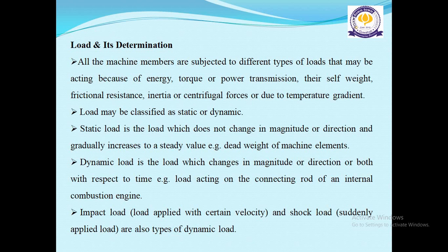Dynamic load is the load which changes in magnitude or direction or both with respect to time. Example, load acting on the connecting rod of an internal combustion engine. Impact load, a load applied with certain velocity, and shock load, a suddenly applied load, are also types of dynamic load.